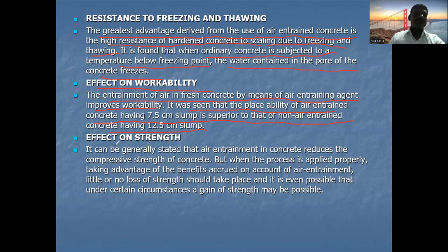Then the effect on strength. What is the effect on strength? Strength is also one of the important properties of concrete. So what effect will there be on the strength due to addition of air entraining agent? It can generally be stated that air entrainment in the concrete reduces the compressive strength of the concrete.